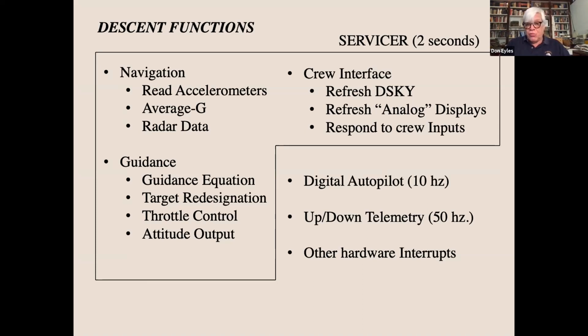up-down telemetry, which transmitted every 20 milliseconds, 2 words of memory to the ground, making a total list over a 2-second cycle, making a total list of, I believe, if I said it right, 200 different words that came to mission control from inside the computer. Next.